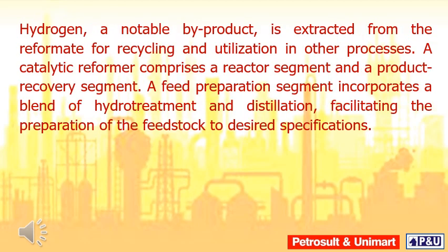Hydrogen, a notable byproduct, is extracted from the reformate for recycling and utilization in other processes. A catalytic reformer comprises a reactor segment and a product recovery segment. A feed preparation segment incorporates a blend of hydrotreatment and distillation, facilitating the preparation of the feedstock to desired specification.